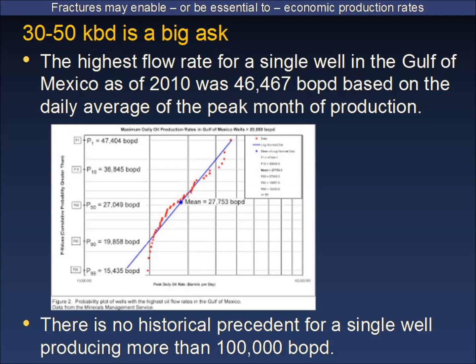Again, I could increase these by a factor of 2 or 2.5 if you like, but I'm talking about the top 50 wells in thousands of wells, even if you think they're all capable of producing at rates that are attractive for geothermal. And we don't stint when we're trying to drill and complete deep water wells in terms of the type of completions and the size of hole that we drill. We drill these things to be big wells, and if they're not, it's because the reservoir really isn't capable of delivery, not because we've got some kind of restriction in the well bore, at least during its peak production times, that would prevent us from producing more.